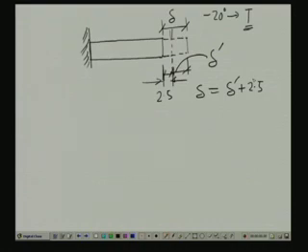Now, our job is to find out the temperature. Since the increase in the temperature is going to cause the deformation of the bar, we will have to find out how much temperature we can allow, so that when it will be encountering this wall, it will be subjected to a compressive force, it will be subjected to a stress, and the restriction imposed in this particular case is that the stress level can go up to 35 MPa.